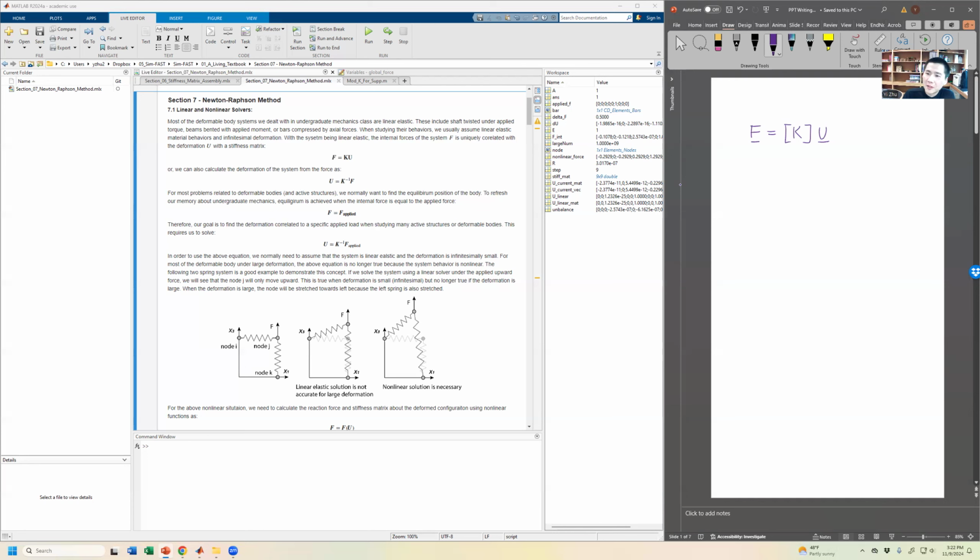Typically, we know that in most cases the force is given, the stiffness is given, and we're gonna need to solve for the U. That's the more common problem we were asked in engineering applications, right? For instance, if I'm a civil engineer, I might have a building, a two-story frame, and the load from the winds would be F1, F2, and I'm gonna be curious about what kind of drift I'm having in the building, right? That's a pretty typical problem.